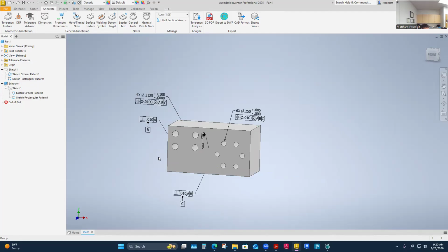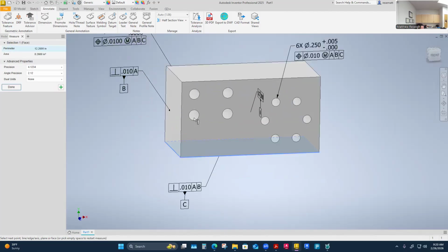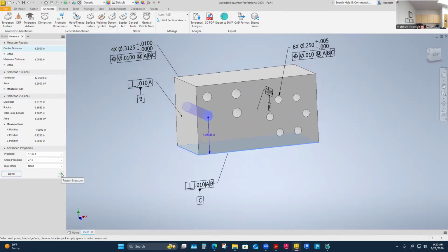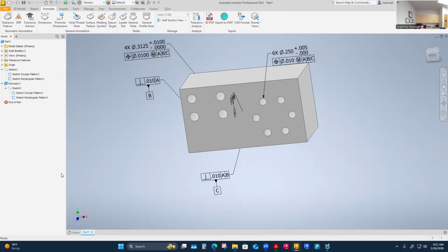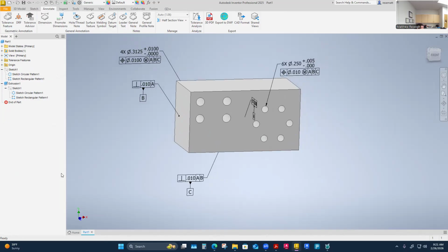I just want to show you that technically I could keep going, and maybe basic dimensions might be the thing they might want here as well. They can measure it though, even their tooling like mine can measure and see how I've modeled this. And in fact, the machine's going to be able to interpret those dimensions automatically anyway. So that might be why that's overkill. It's almost for a visual inspection more than anything. The machine's already got that data in it because I have modeled it at its theoretically exact locations, right?